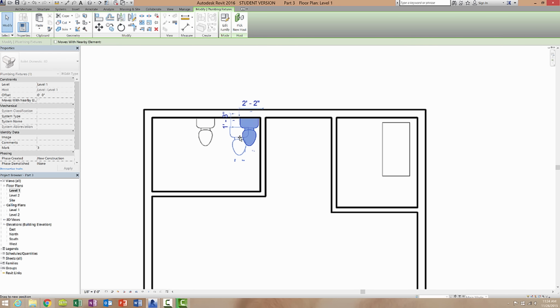If you notice, while holding the toilet, Revit tries to help us by positioning it where we want across the wall. We can get very specific with how we place it. We can let it go. We can use the keyboard as well to tap it into place if you're trying to get something very specific. And we can also use the Align tool located right over here.